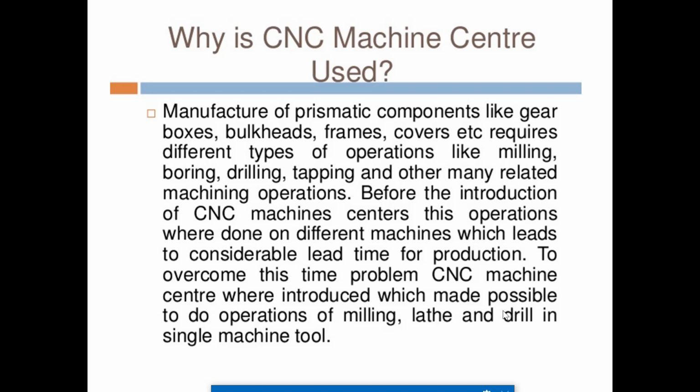To take the component from one milling machine to the tapping machine, one laborer has to lift the component, go to the desired tapping machine, keep it there, and again set it for a work table or desired platform. That increases the lead time and consumes more time. That time can be easily reduced by using a single CNC machining center.